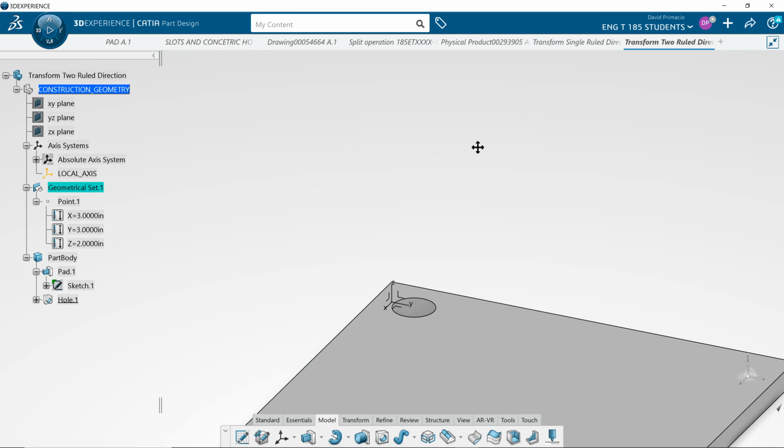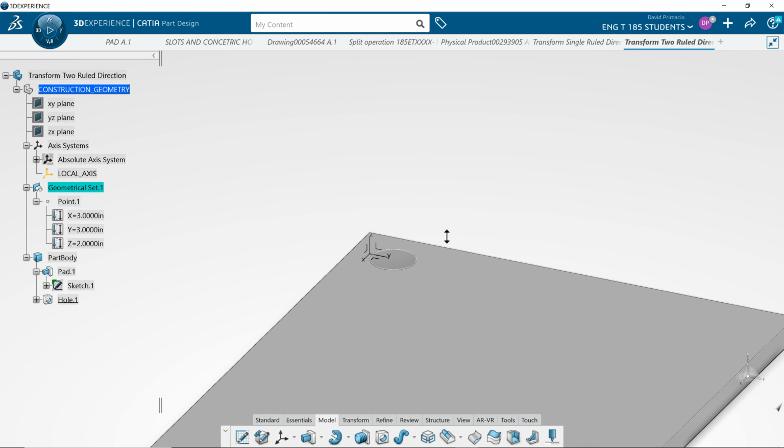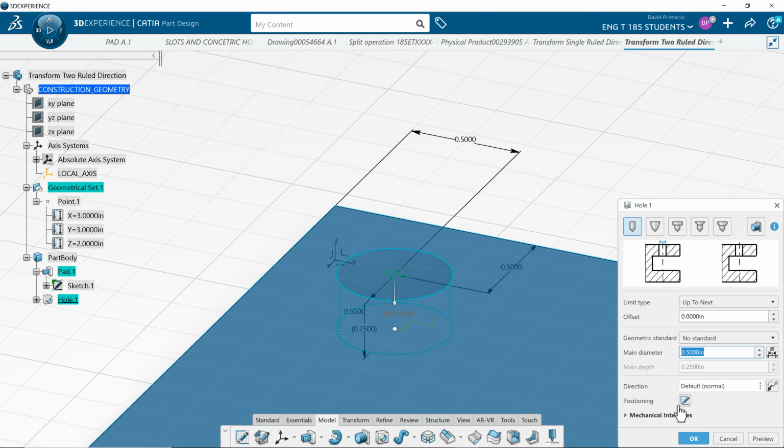Alright, so if you ever miskey in a value, you just double click it, and then you can get that pop-up window to come up and you can change whatever you've done. We'll go 3/8 again. I'll hit enter. Now I got a 3/8 inch hole.